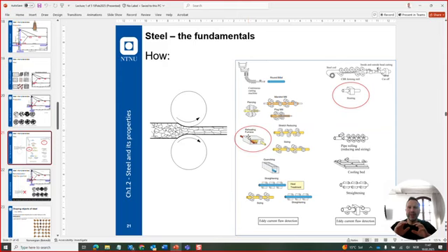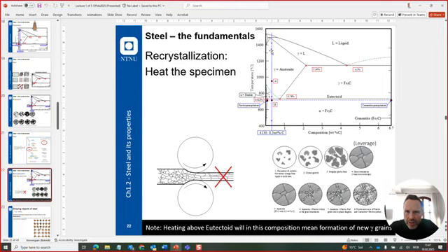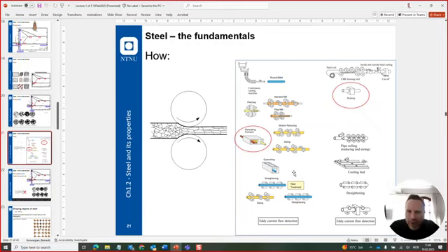You keep it at this state, you work the whole specimen or pipe up here, you keep the temperature. As it goes down, it will keep as if the grains never were elongated, so you rework the microstructure. You can also do it by quenching or cooling it off and then reheating it and then recrystallizing. You have multiple options.